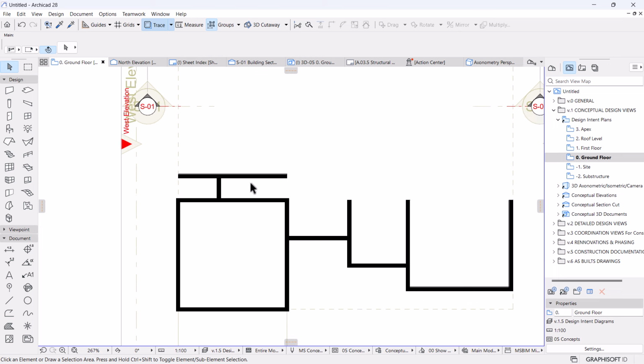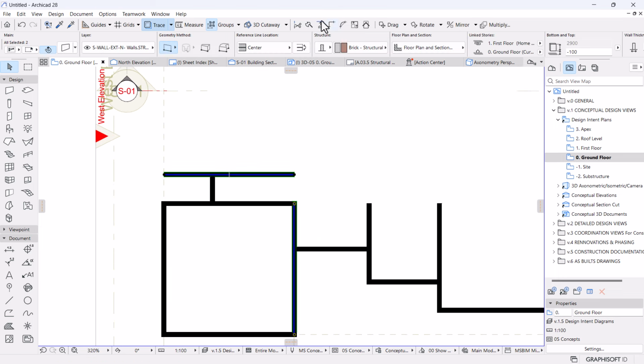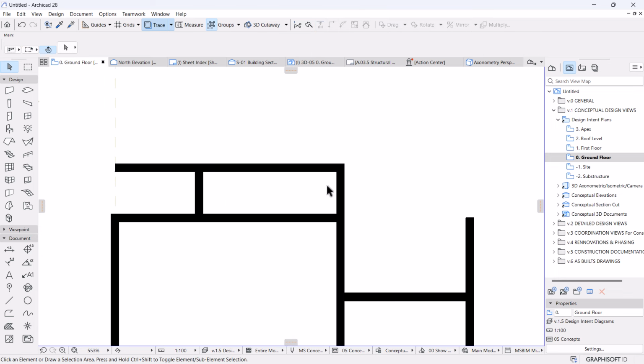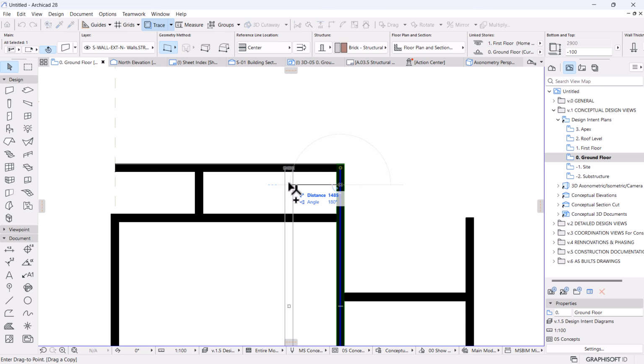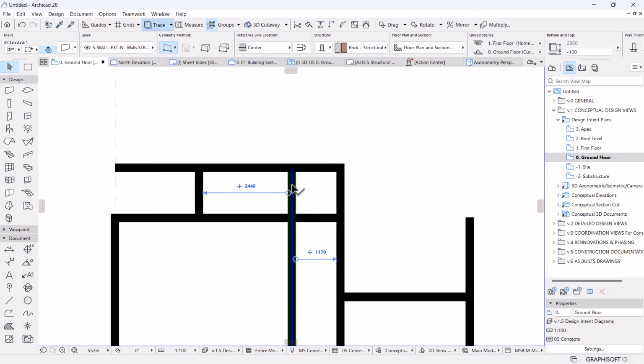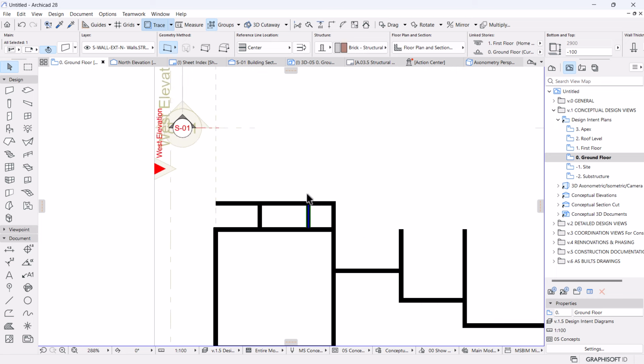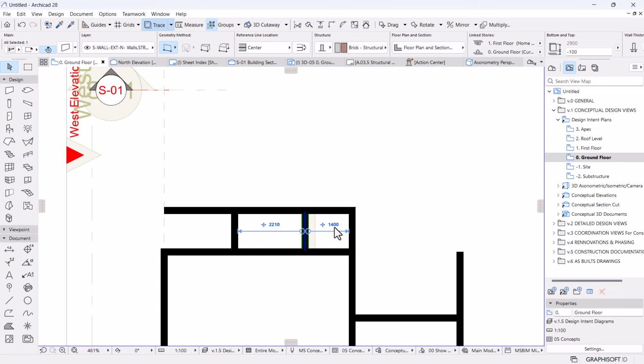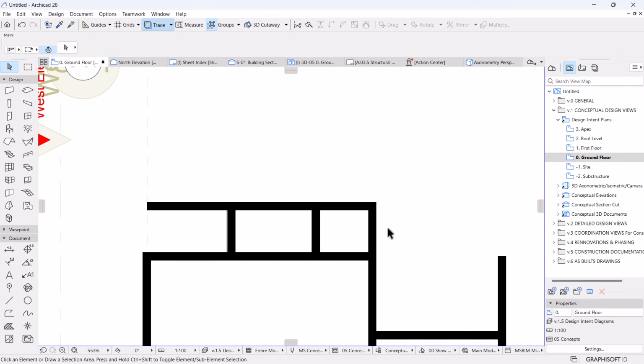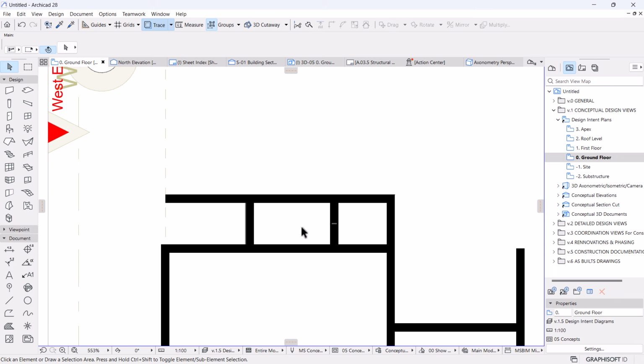Okay, let's move ahead. The powder room, so this wall, obviously it will go across like that, and then I will create a little bit of a passage, a little bit of a lobby here of 1.4. I'm going to trim this that way. Let's have it to 1.4, the internal dimensions. Okay, so this will be the entrance. This will be the lobby for the access of the staff room and the powder room. Normally the walls for this are internal walls, which are half the thickness of the exterior walls, but for now I'm not going to be bothered much about that. It's something that can be addressed in later stages of the project.